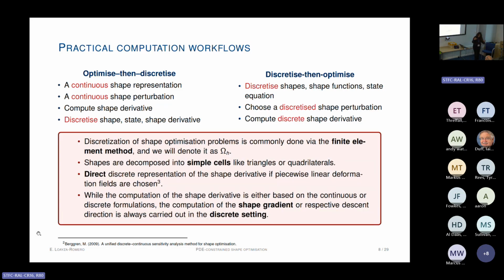As for computational aspects, this is definitely not the only method, but one way of doing it is by using finite elements. Why? Because, in the way I see it, you need exactly the same mesh or triangular decomposition of the domain to represent the changes in shape, but also to solve the PDE there. There are other ways of doing it, of course. For example, you can have one mesh to deform your shape and then initialize a new triangulation in order to solve the underlying PDE to obtain your state equation at this particular point.